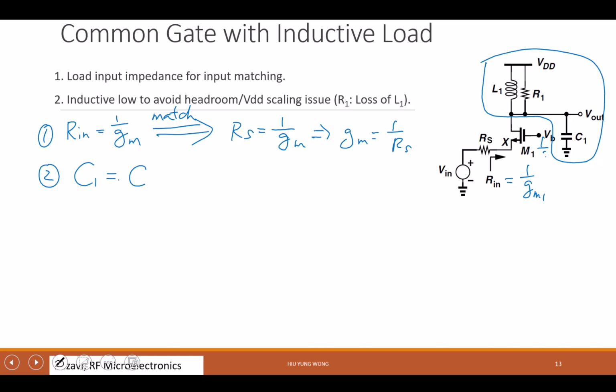When I talk about parasitics, you can probably tell me, right? It is the output capacitance. I just call it output capacitance. This can be CDS, CDG, the drain and gate overlap capacitance. Remember what I said in the last lecture? Or maybe also including the CDB, the body to drain capacitance. Okay?